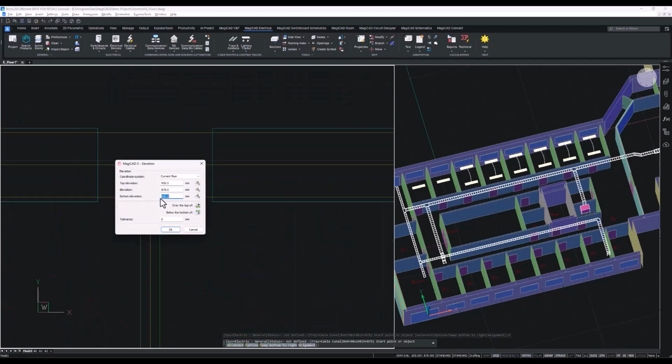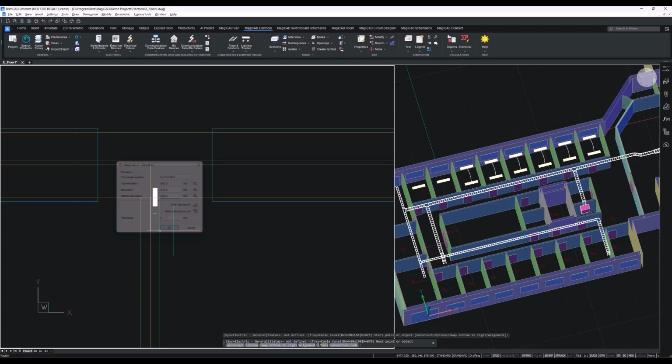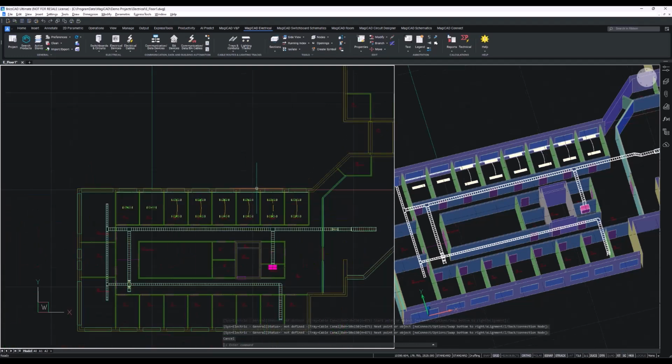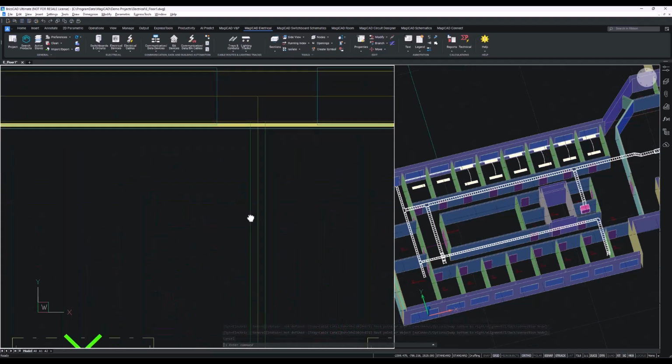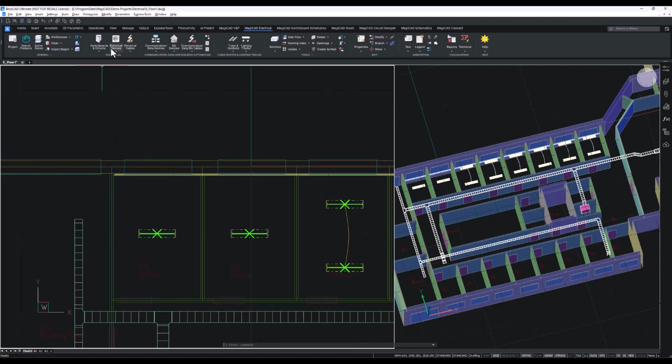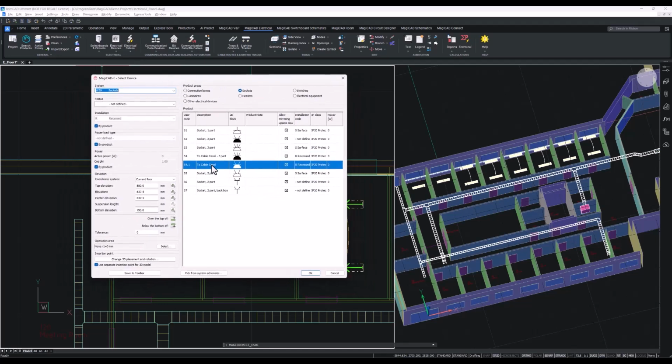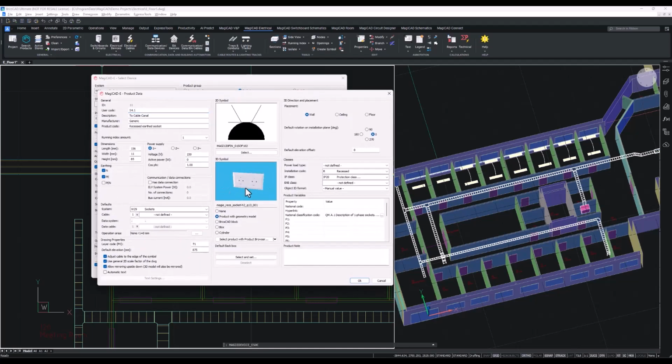And let's start drawing. Also, I'm choosing the elevation. 800 millimeters is fine. And right now we are ready for the socket installation to the cable trunks. So let's go to the socket menu. Here I'm going to choose to cable channel product. So it looks like this. Here you of course can change some settings such as dimensions, system, power supply, earthing, etc.